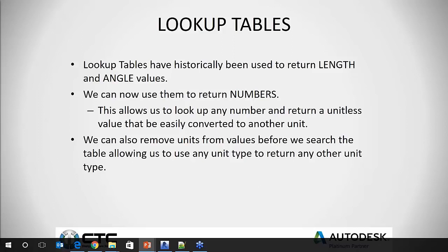As you saw, we can pull in horsepower information, we can pull in breaker size information, whatever it is that you might want, as long as it can be used as a numerical value and then multiplied by 1 to get your units and add those back in and populate your values in your schedules.